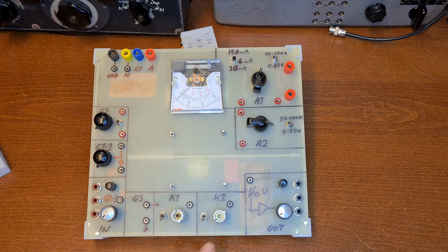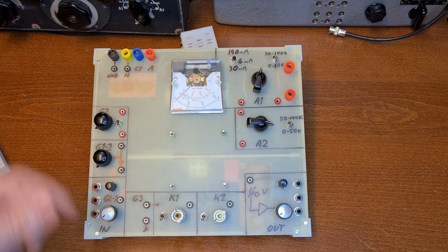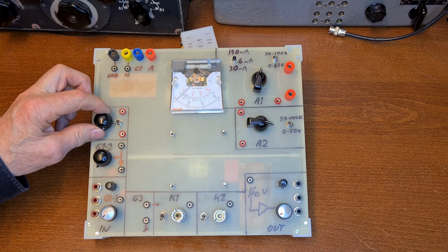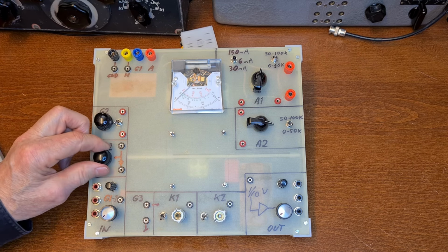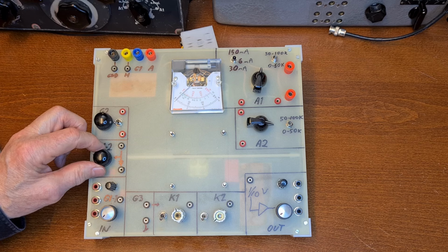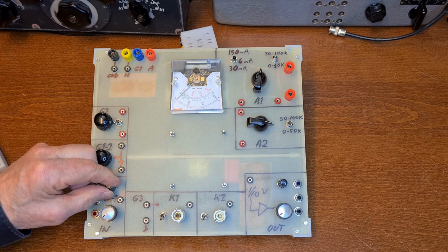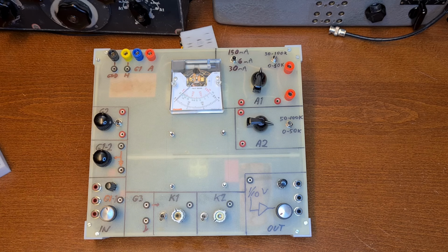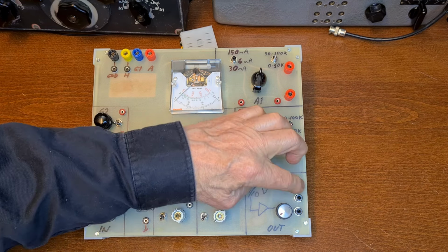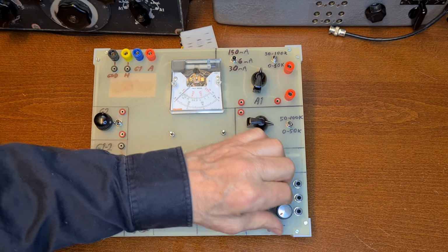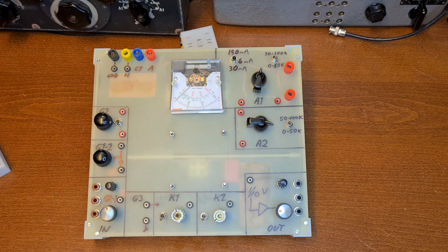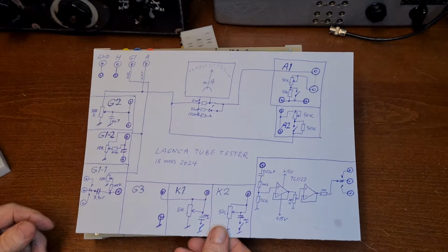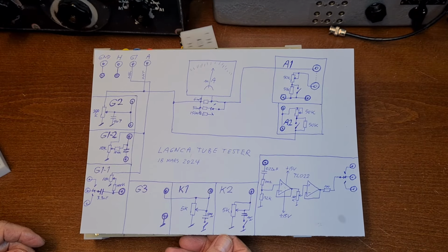These are the cathode circuits. 2 for double tubes, consists of a 0 to 5,000 ohm resistor and a capacitor. Here grid 1 and grid 2 circuits. Here is grid 1 circuit. It also has an input selector, so you can easily choose a signal generator, music, or audio analyzer. Here is the output signal circuit. It also has an output selector, so you can easily select oscilloscope, music, or audio analyzer.